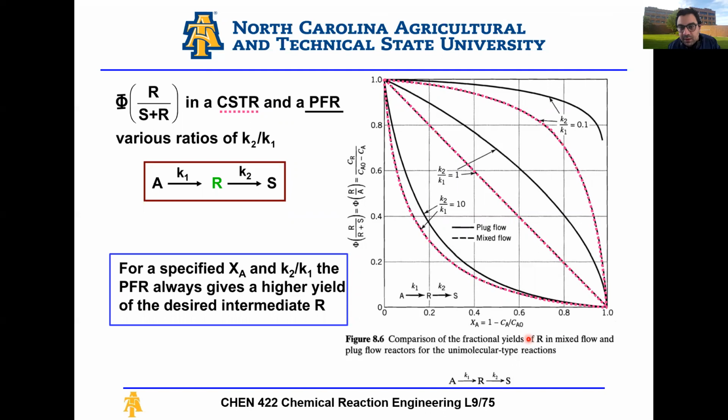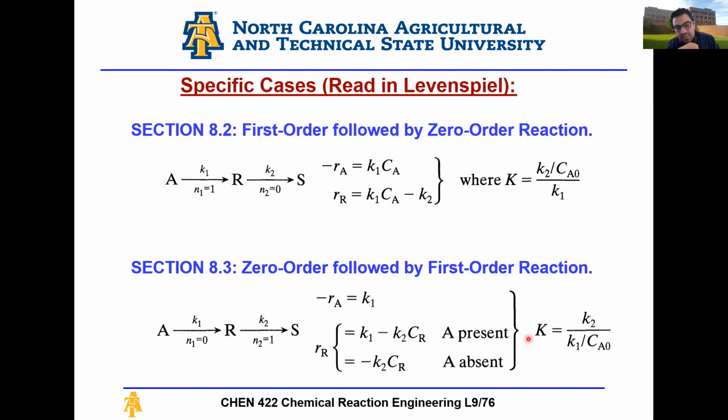And in other specialty chemicals, you see CSTRs a lot, making lubricants for cars, or companies that make additives, where you really need to have very fine control of your concentrations, of the nature of the chemical, of the rate of polymerization, etc. Whereas in oil and gas, for example, you're just pumping product all the time. You operate within margins which are somewhat loose in terms of product quality, then you always have PFRs operating alongside distillation columns, right?